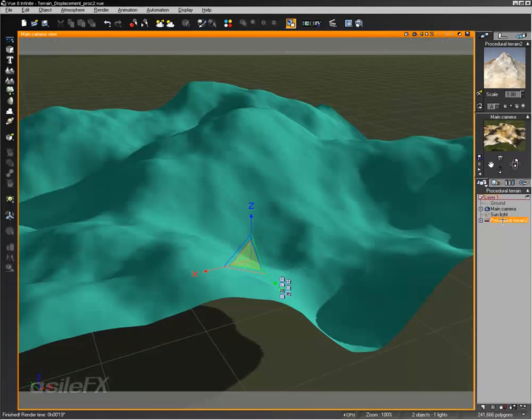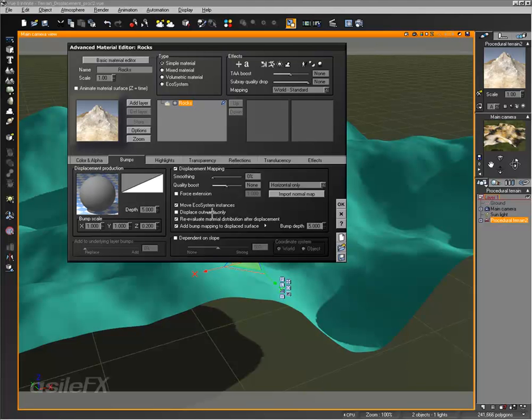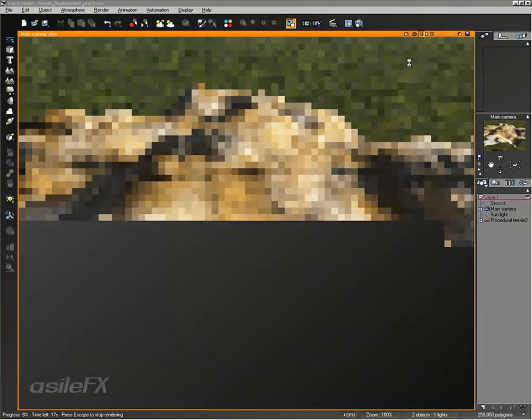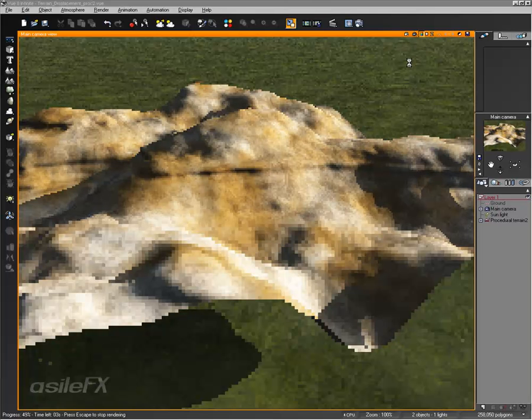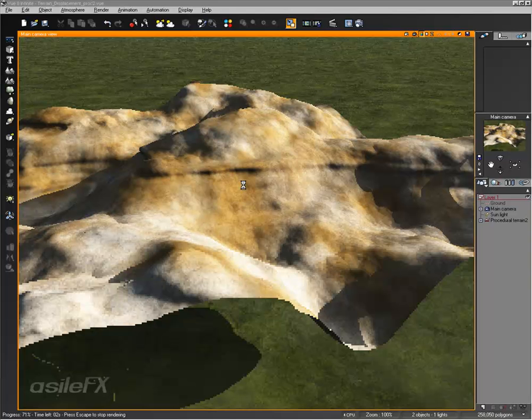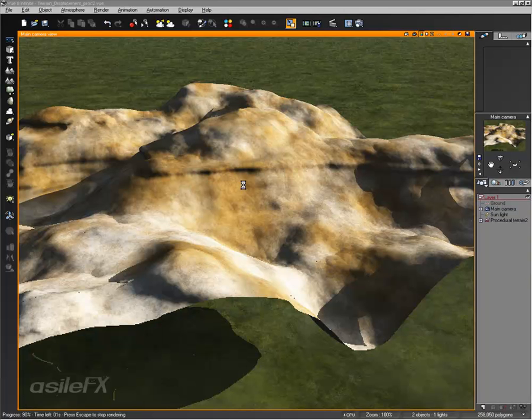So there's an option to displace outward only, or you could force the extension beyond 1, starting at maybe 3, and that will displace it outward a little bit more, and that can sometimes help remove those overlaps, because the entire surface is then being displaced outward for the most part. It's another way to displace outward, but you're forcing the extension, so you're extending the overall geometry output.